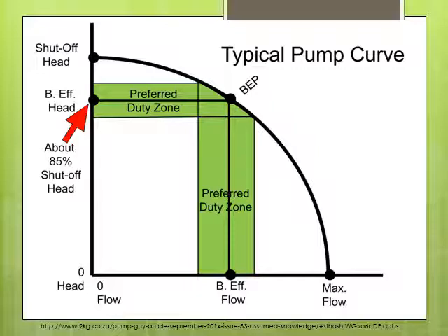And that means that the pump is always turning on and off and on and off, which is going to burn it out. So usually you try to size the pump within a certain range, about 85% of your capacity. 85% of the pump's maximum capacity is your sweet spot for the size you're going to get.